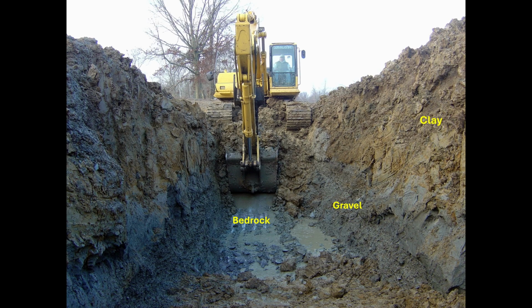The core trench is based on a firm and impermeable layer of shale bedrock that is made wide enough for a medium-sized dozer to enter. Note how water is pooling in the bottom of the trench? This is a good sign. It shows that water is not soaking into the ground. The core trench was dug to be from 18 to 26 feet deep.